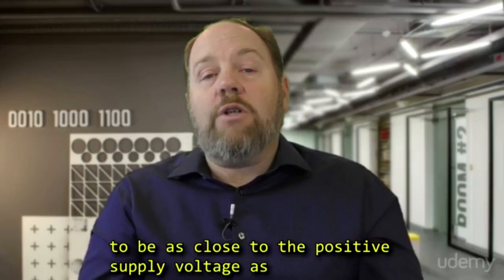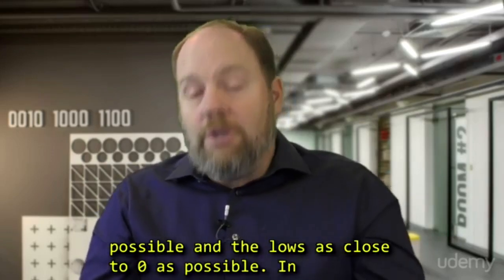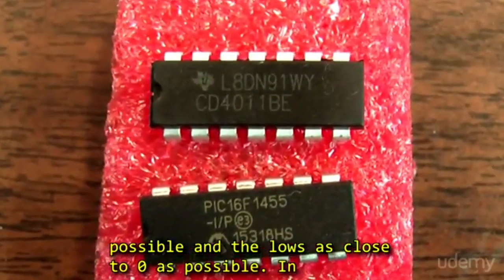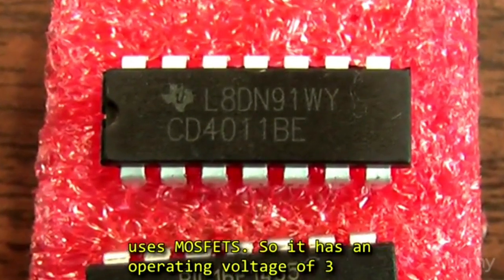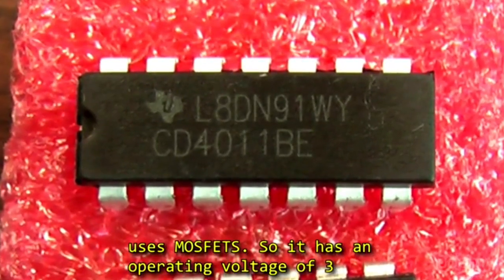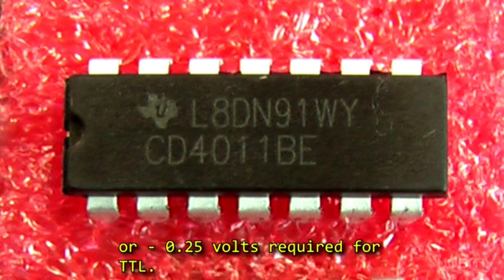Your highs need to be as close to the positive supply voltage as possible, and the lows as close to 0 as possible. In your kit, you have a 4011 quad NAND gate chip, which uses MOSFETs. So it is an operating voltage of 3 to 15 volts, far less stringent than the 5 volts plus or minus 0.25 volts required for TTL.